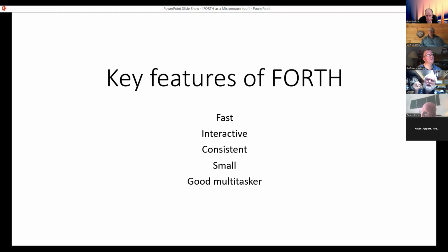So I can turn the speed up a bit and see how much effect that has, perhaps turn up the proportionality constant, see I've made it wobble a bit, turn up the derivative and smooth out that wobble. And I can do that interactively until the mouse is just on the point where the tires would break away. You can really get that mouse to hang out on the corners. It's really impressive.